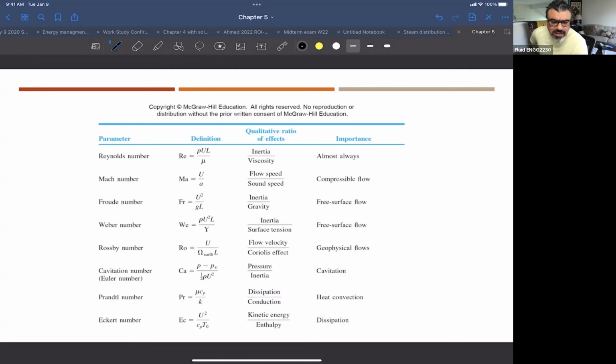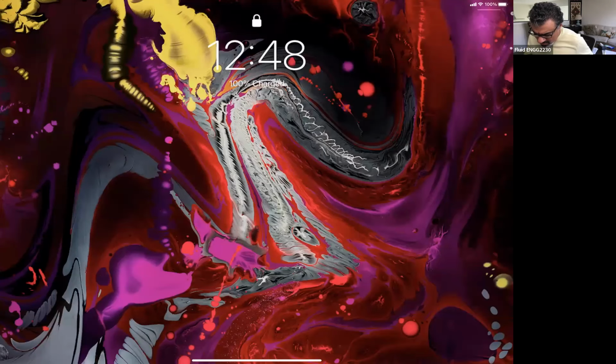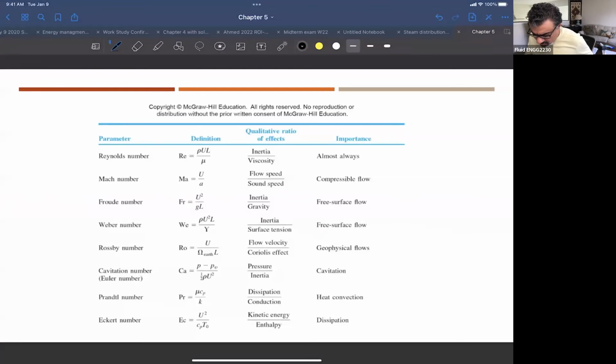You don't have to do a whole large number of analyses after you come up with this non-dimensional parameter, because other people have done, for example, the effect of Reynolds number on sphere drag and so on. So you don't have to create your own number that has a different shape. You're trying to find a reasonable, common, famous number that you can utilize to use other people's data. And that's the idea, right?